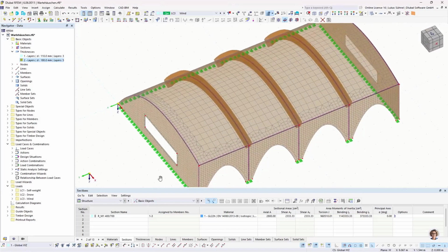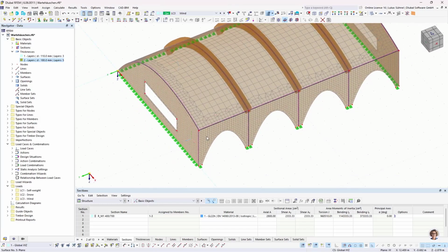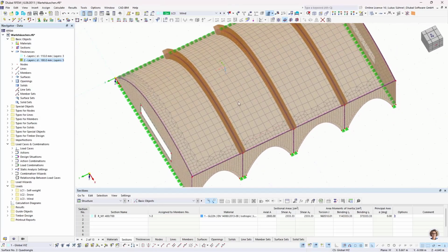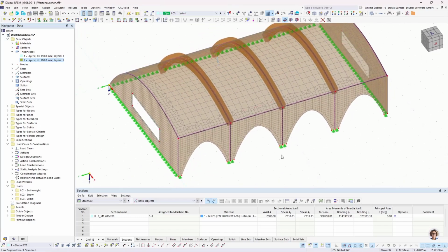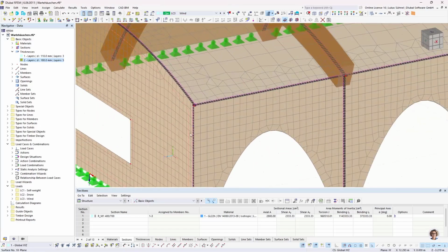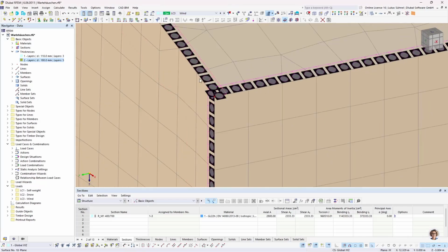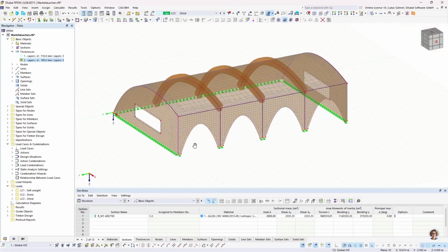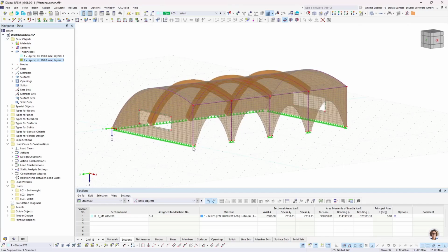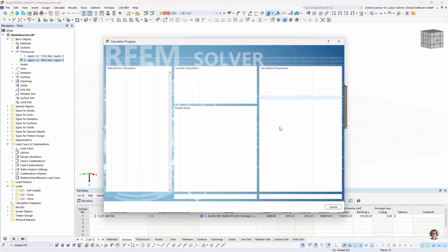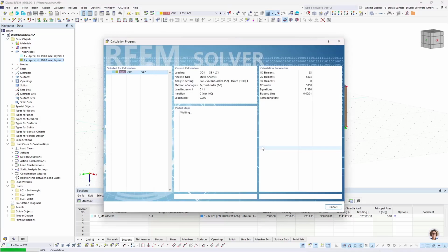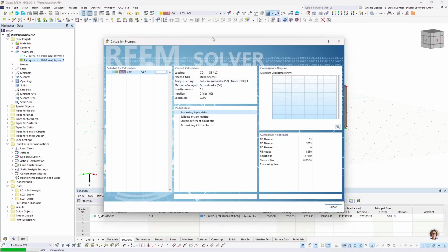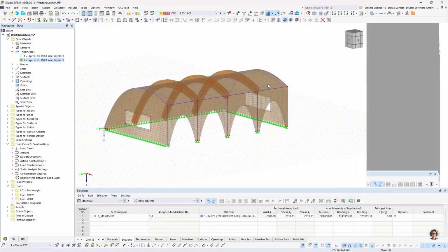But you can clearly see that the mesh refinement has been defined on these walls, except for the roof where I have the global FE mesh settings. And we can also see that I have these line hinges defined, and all the things that I showed here. And if everything is fine, we can also run a calculation and we can get the results. And this step, running the calculation, can also be triggered via the Grasshopper component. So that's also possible.